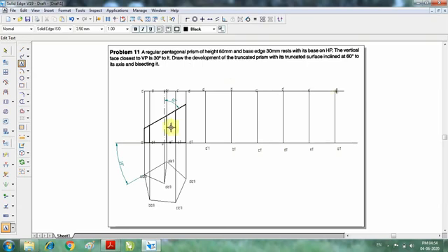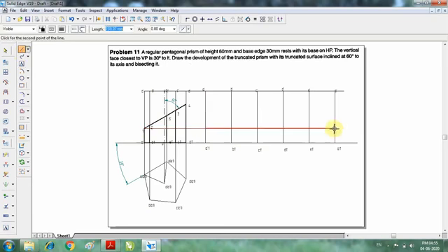Now from this you can see that none of the sides has been cut, only the lateral surfaces have been cut, so it will be easy to draw. I'll go for naming that. A1 and A has been cut at point 1, B and B1 is cut at point 2, C and C1 has been cut at point 3, D and D1 has been cut at point 4, E and E1 is cut at point 5. So I'll go to project. A1 is cut at 1 on both sides.